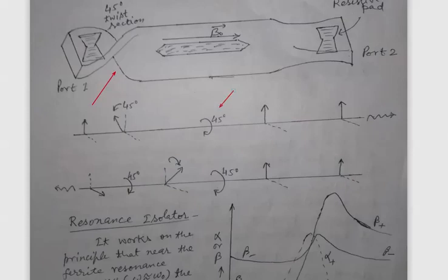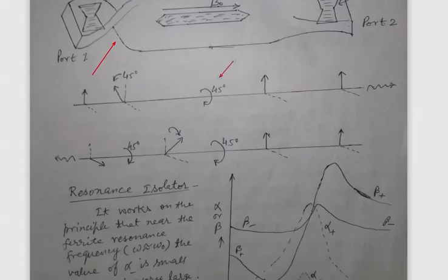The ends of the ferrite rod are tapered so as to reduce the possibility of direct reflections from the edges of the ferrite slab. In both the input and the output rectangular waveguides, two resistive pads are placed, and we will discuss the importance of these two resistive pads.